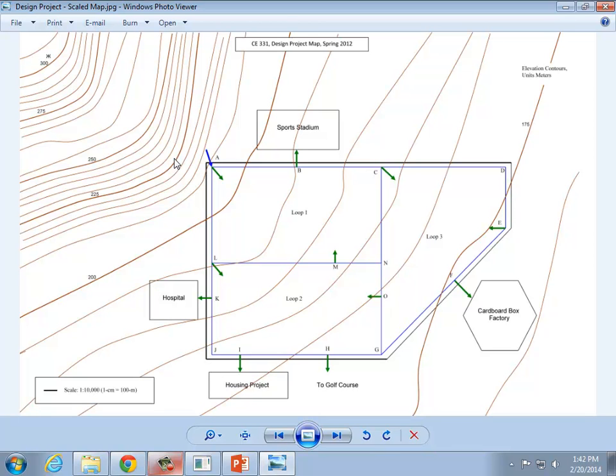And so the peaking factor tells you the ratio between the peak day and the average day is 1.8. And then the peak hour to the average day is 3.25. And so if your average day flow rate is 100 liters per second, that would mean that the peak hour of the peak day, the flow rate demand is going to be 325 liters per second.